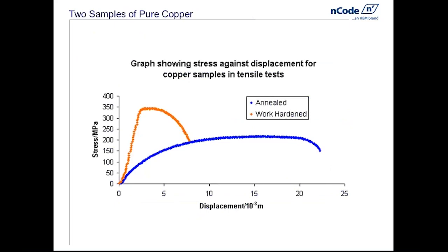Let me give you an example. We've talked about soft metal and hard metal. Here is one that I've pulled off, annealed and work-hardened copper, just to show you the difference. On the lower left, you can see that the yield strength of that annealed copper is very low indeed. But once you work-harden it a bit, it gets much higher. And the other key point that I would like to show you on this, which of course has direct relevance to the fatigue performance of these materials, is that the ratio between yield strength and UTS is very different for the work-hardened and the annealed material.